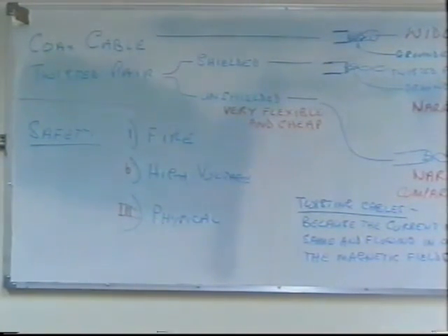That goes to SF6 breakers, stepping it down through transformers to 34 kV, and stepping it down more until it reaches the heater coils, about 800 volts, but with 30 kilo amp or 60 kilo amp, 80 kilo amp. That's a high current. The whole building starts to vibrate and the coils go down.